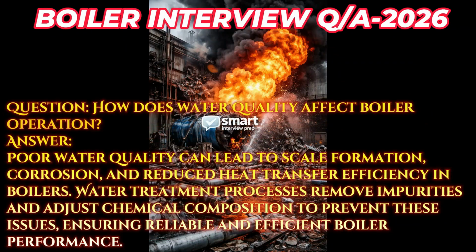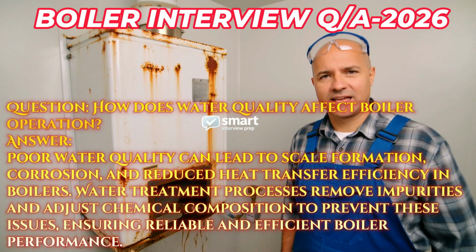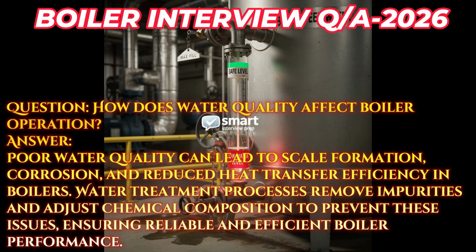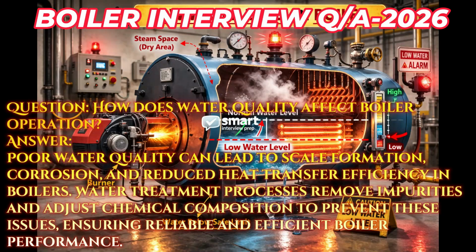Question. How does water quality affect boiler operation? Answer. Poor water quality can lead to scale formation, corrosion, and reduced heat transfer efficiency in boilers. Water treatment processes remove impurities and adjust chemical composition to prevent these issues, ensuring reliable and efficient boiler performance.